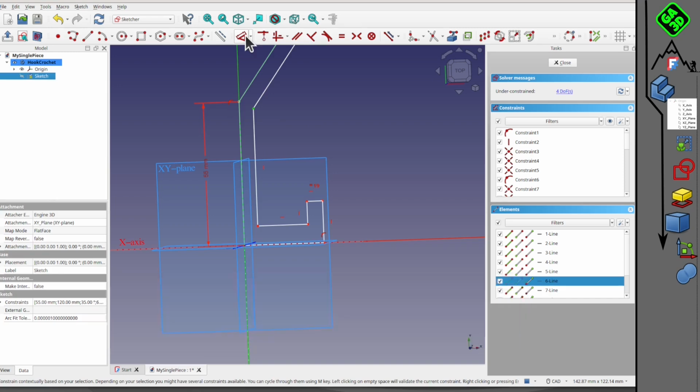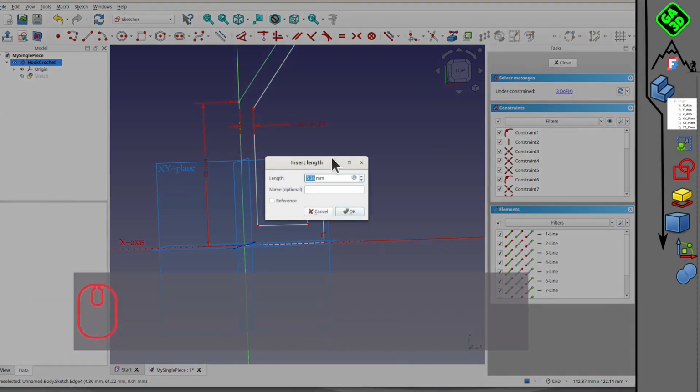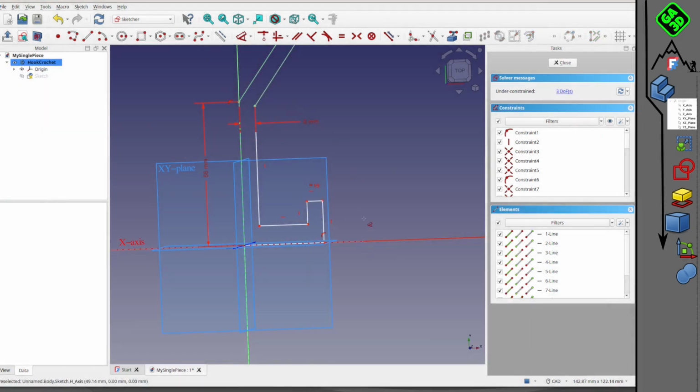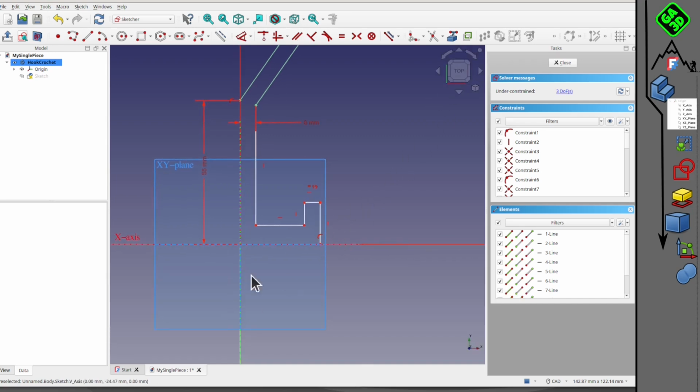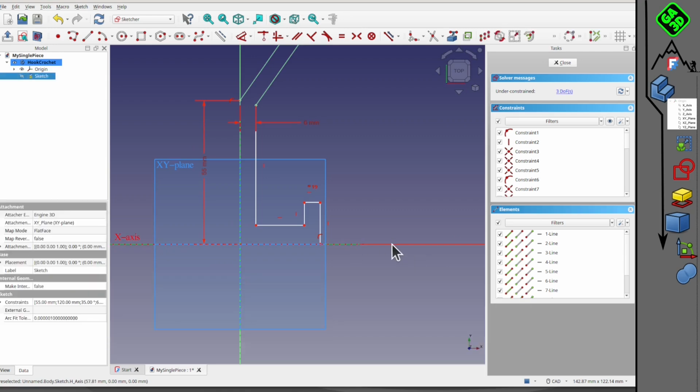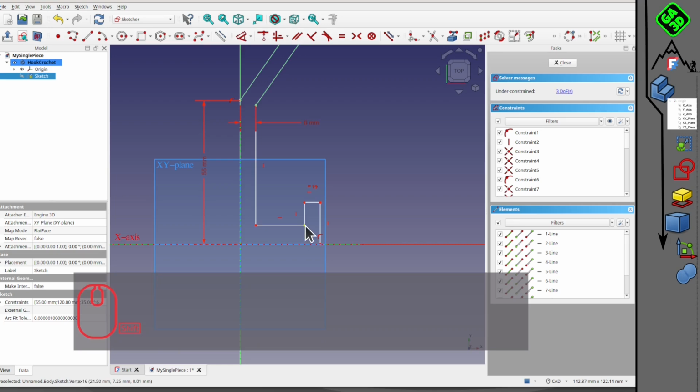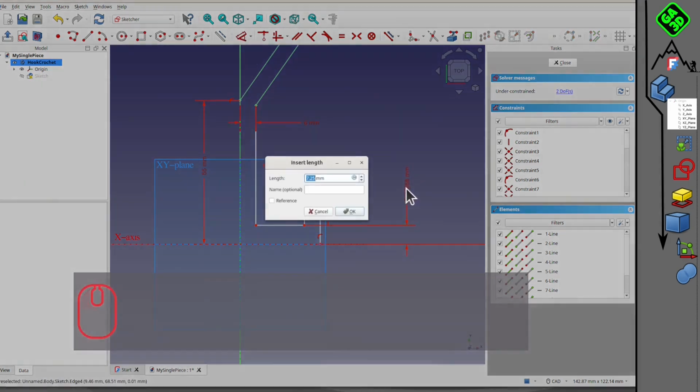Now we've got 7 mm. I want 6. There you go. So this is good. We're done with this. What's left for us here? We can see that we still have 2 dimensions that are not constrained. So it's that height and that dimension. So, my sketch in design. I like that part. So here, I'm going to define that little height.